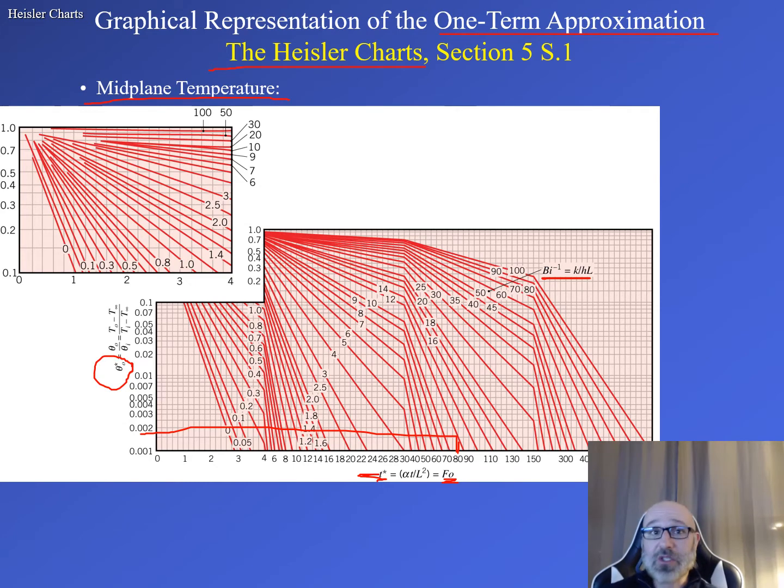So we can utilize these charts, but again, this is a very small condensed chart, and this is only going to be an approximate solution when we use these charts. But they are a good double check, a good reference if you've done this out by hand with the other methods that we saw above and actually worked out our calculations. We want to double check and make sure that it is similar to what we're seeing on these charts. This is a great double check as a reference, to use these Heisler charts.